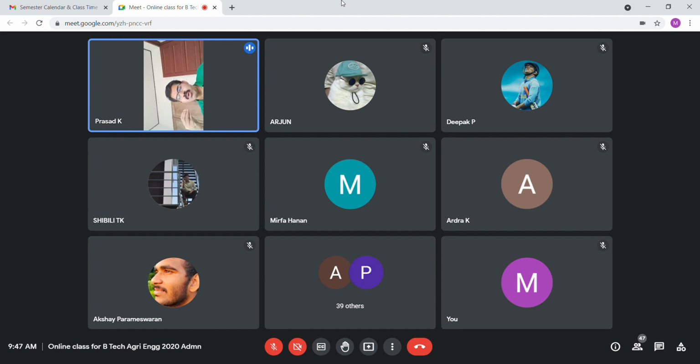And while considering the module, with respect to Indian standards, different types of modules are available, that is, 1, 1.25, 1.5 to 2.5, like that. While we are making a gear, we generally have some module. The module of our gear is 1 or 1.25, like that. That is a standardized one. So while making a gear, we generally use standard module values, that means 1.25, 1.5 to 2.5, like that.